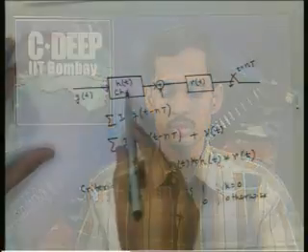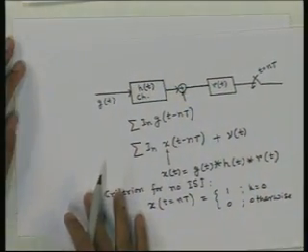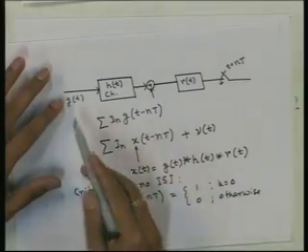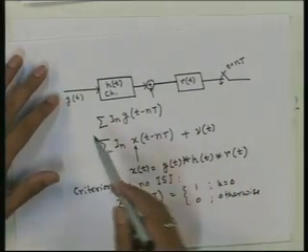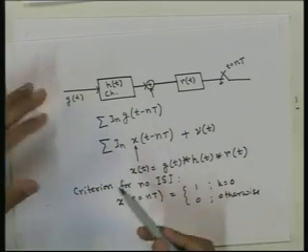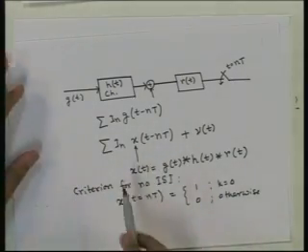One such reason is that the channel itself may change with time, and as a result it may be difficult to adaptively design g(t) based on what the channel is. If the channel changes slowly or fast with time, the g(t) for ISI free transmission needs to change with time, and that requires difficult dynamic design of the pulse g(t).